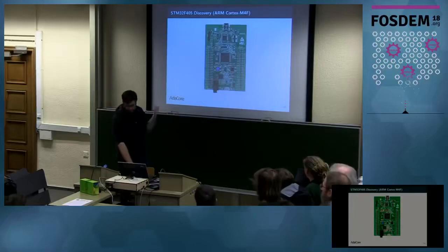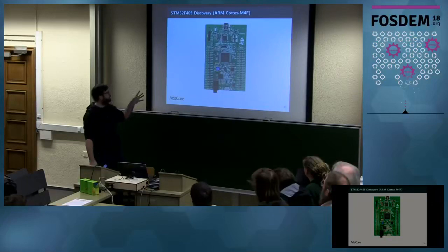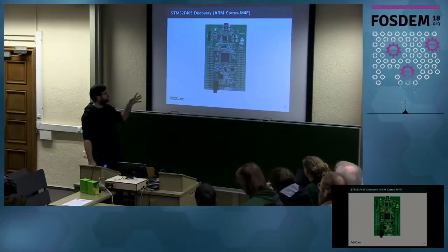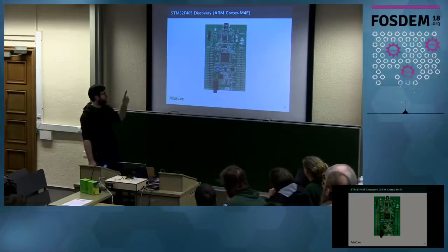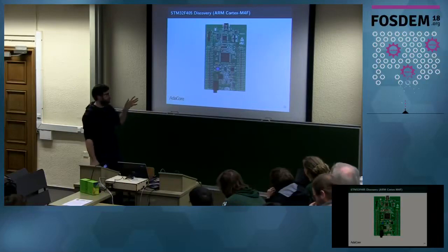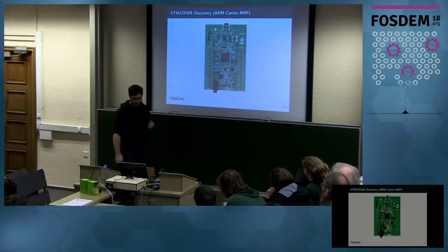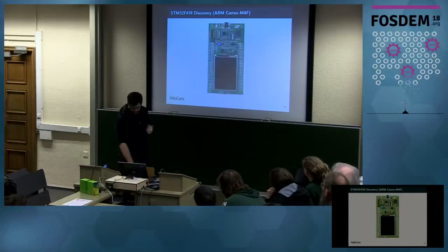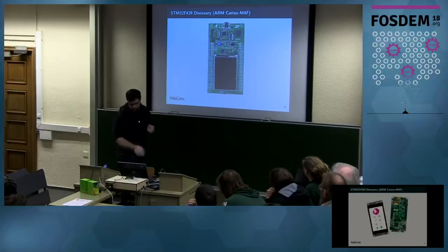So I have here the list of boards that we support. I will just spend a few seconds on them. This is a really good option to start. It's one of the boards that we support the most. It's an STM32F405. This one is really cheap, like 15 euros or something like that. But you have everything you need. There's a debugger integrated, a really powerful microcontroller, and as I said, that's one of the boards that we support the best. You then have this one, which is more or less the same, but with an LCD screen and touch screen as well, which is nice.